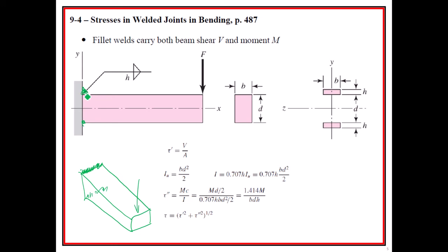So it ends up being, here's the little triangle of the weld on the top and the bottom. And obviously, this part right here is going to be in tension, and this part's going to be in compression. But we still pretend, and this is really weird, that this is the joint that it's going to be shearing along, right? That the shear stress that we're looking at is actually through the throat, because you'll notice that 0.707 shows up again.